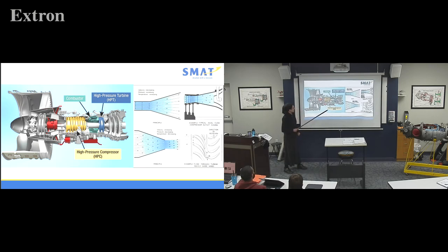And then, what do we have right off of our combustor? What's the very next thing that comes in? Stator. Excellent. Stator vanes. What are some other names? Nozzles. Diaphragm. Inlet guide vanes. Excellent. So the very first ones are turbine inlet guide vanes or turbine inlet nozzles.